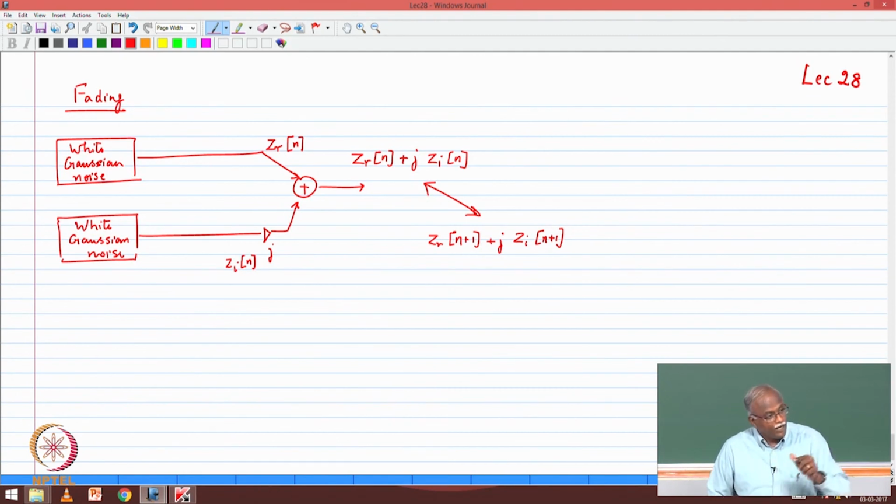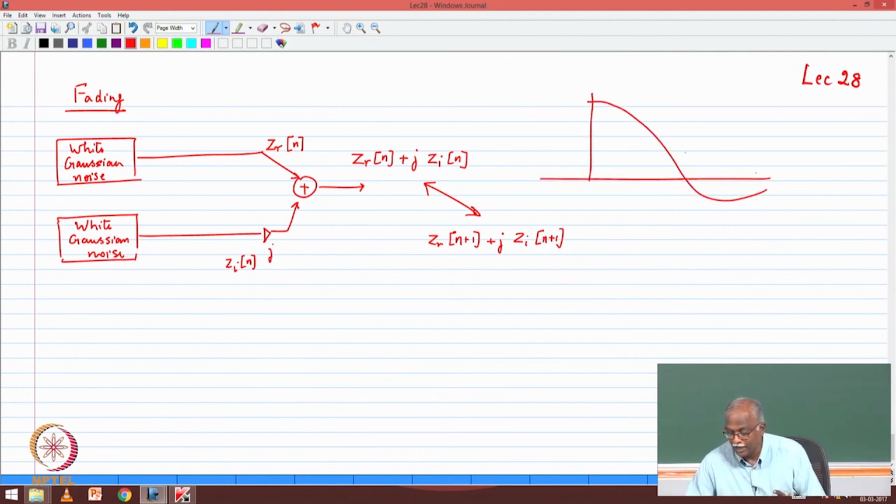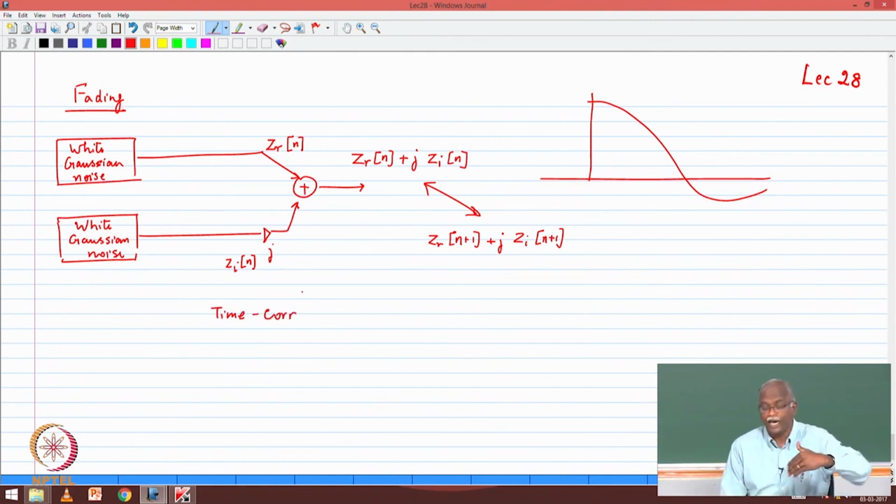But now, if I am in a fading environment, and I just moved my time of observation by a few milliseconds, and you say the channel completely changed, no, that's not possible, because you know that the autocorrelation function is actually a Bessel function. Until you reach coherence time, the channel has to remain correlated, but this is totally uncorrelated. So the question is, this is okay because it will generate the right Gaussian, the Rayleigh statistics, but it does not capture the time correlation. How do I ensure that the samples are time correlated?